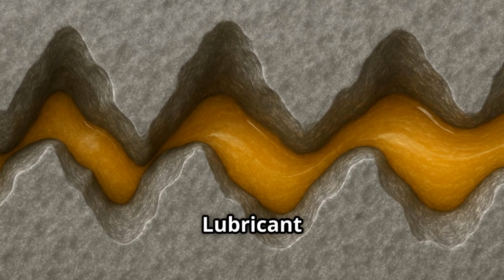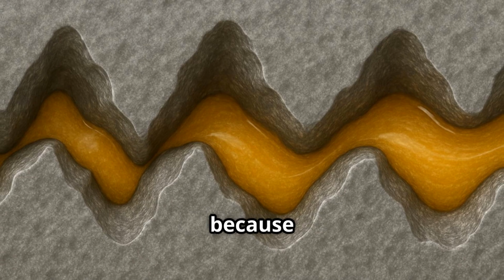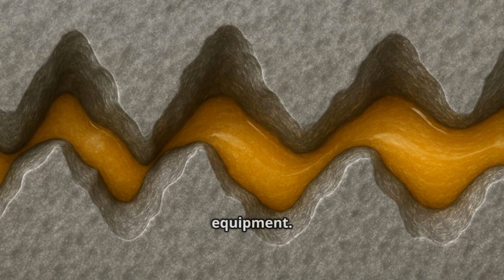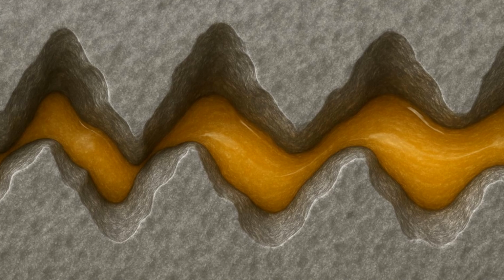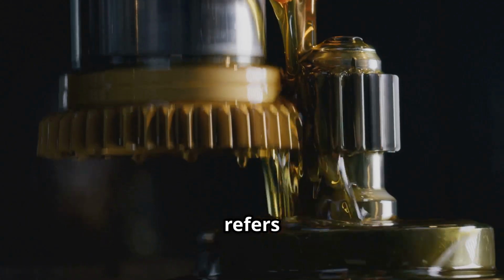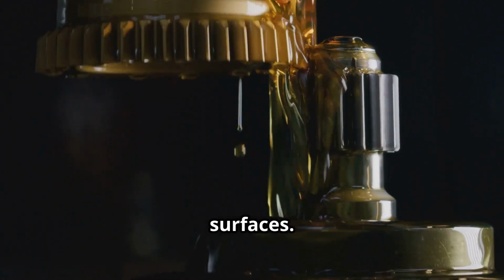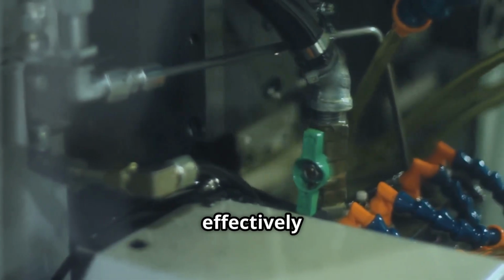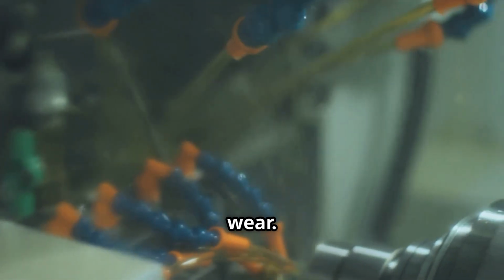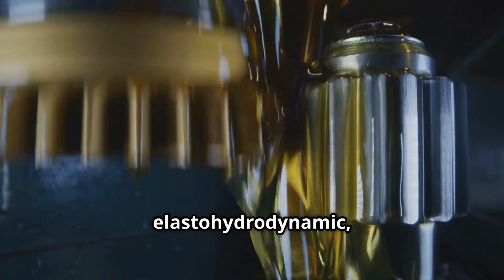Let's talk lubricant regimes. Understanding lubricant regimes is important because it directly affects the performance, reliability, and lifespan of mechanical equipment. What is a lubricant regime? It refers to the different conditions under which a lubricant operates between two contacting surfaces. These regimes describe how effectively the lubricant separates the surfaces and reduces friction and wear. There are 4 lubrication regimes: boundary, mixed, elastohydrodynamic, and hydrodynamic.